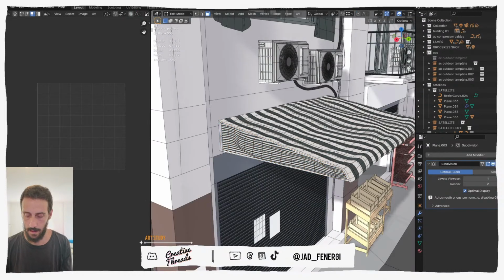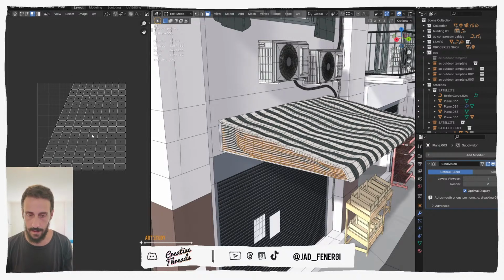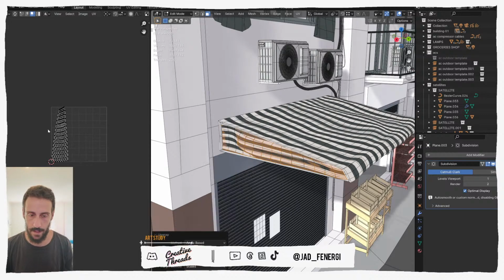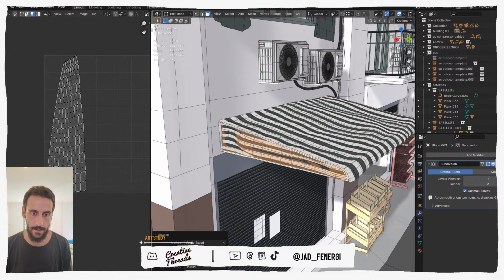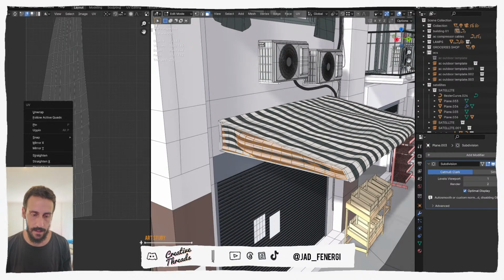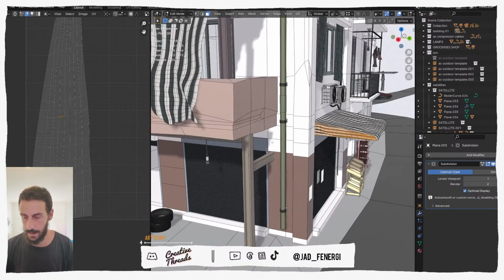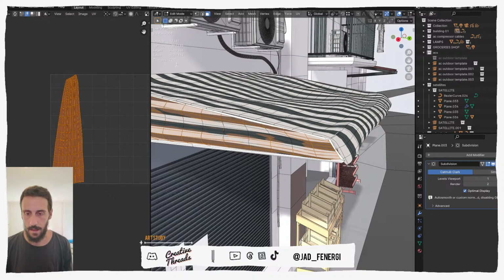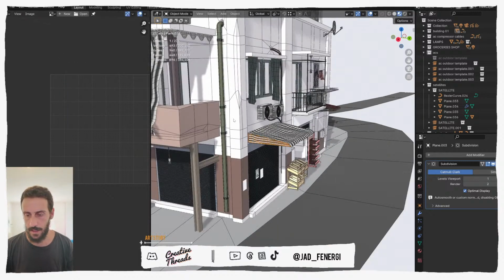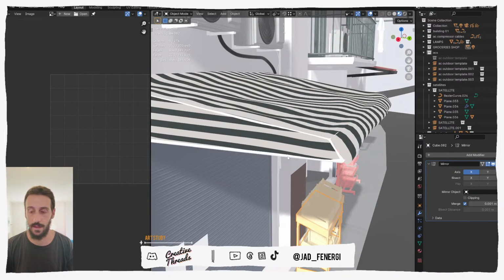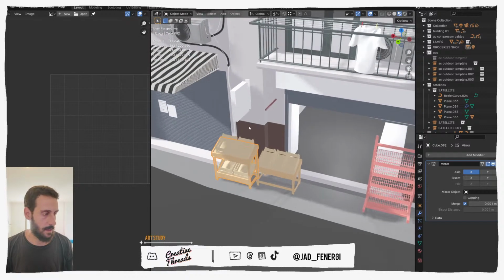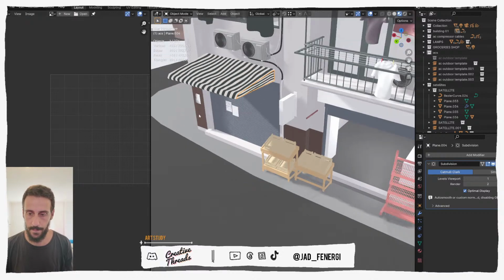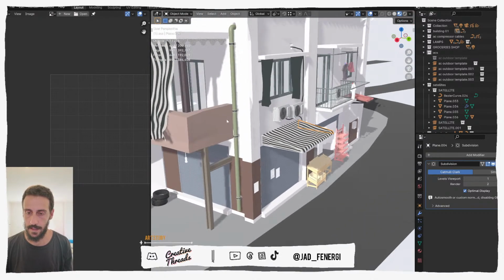So tab, yeah, select all the faces, press U, unwrap it, and then let's also fix this. Let's auto align. I don't think we need to flatten this out, actually. It's fine. Yeah, this is fine. It's already following the shape. And also the orientation is okay. So just an unwrap for this did the job, I think. So let's keep it like this. Let's move on here. Press A, U, unwrap, and that's it. So this is for these guys.